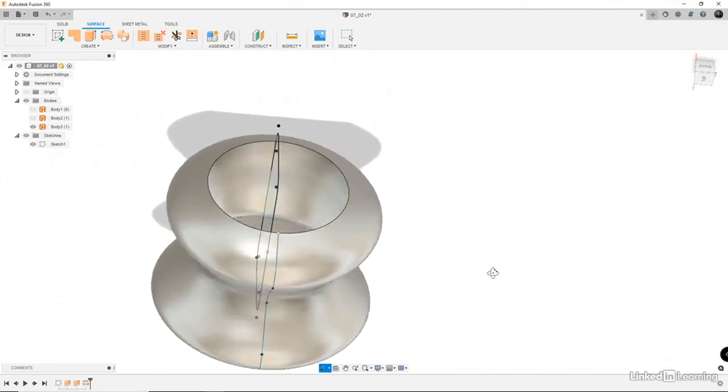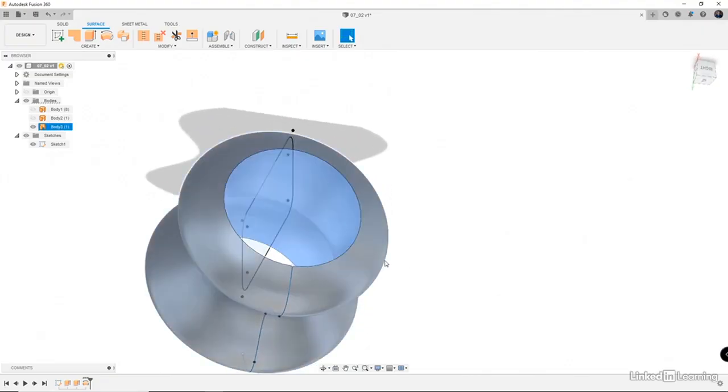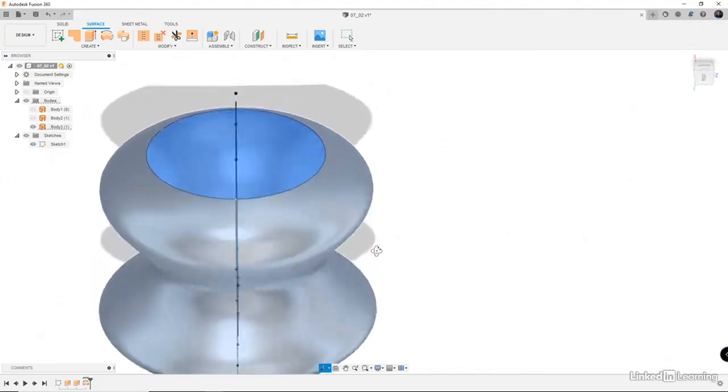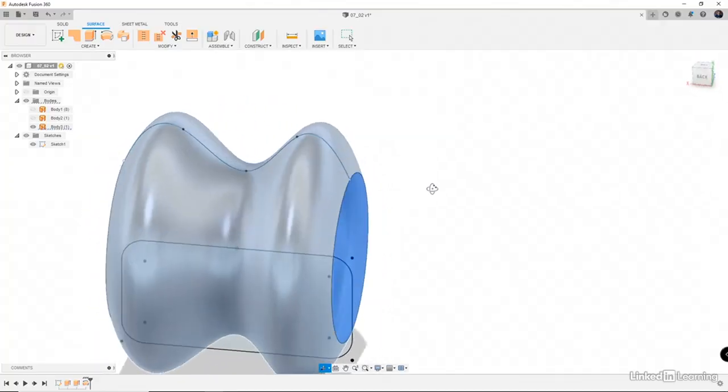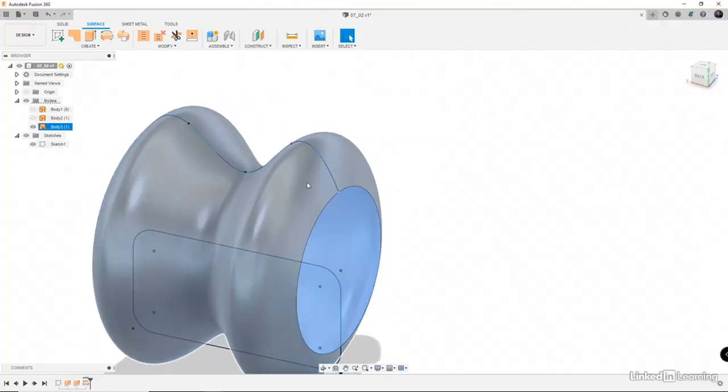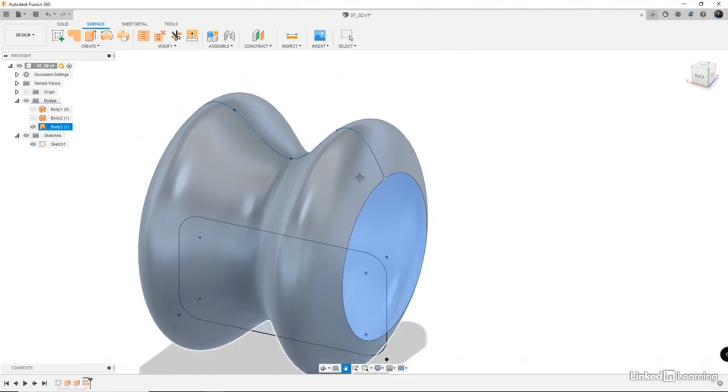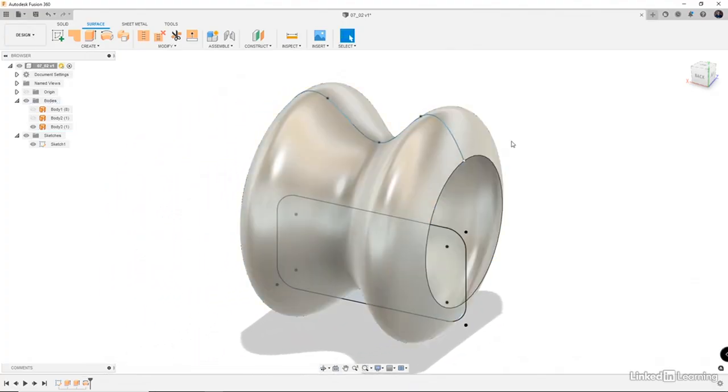And this is a surface only. It has no thickness. Again, we can use this as a cutting tool. We could also do it if we were going to do some composite work and we wanted just the surface. We didn't want a thickness. We're going to add that thickness in a composite tool set. This is something we could do. So there's many uses of why you want a surface, but we can use a sketch to drive both a surface as well as a solid body.